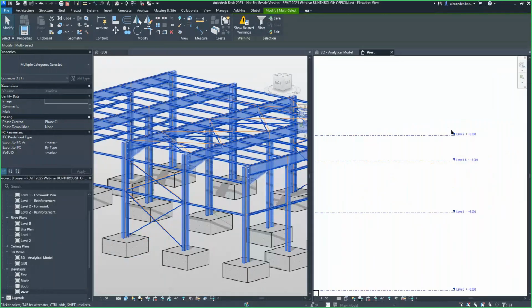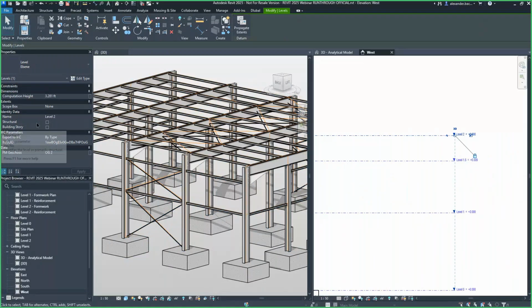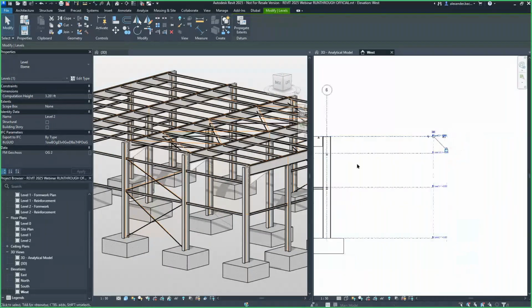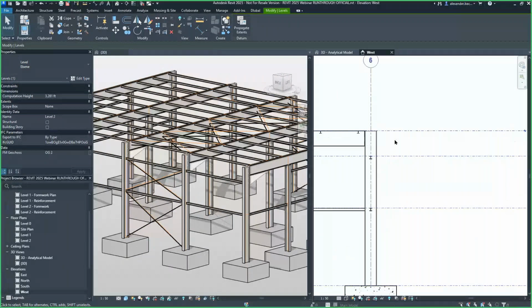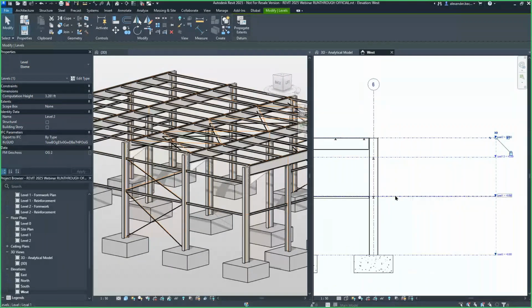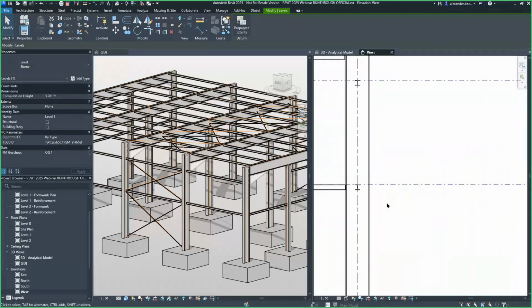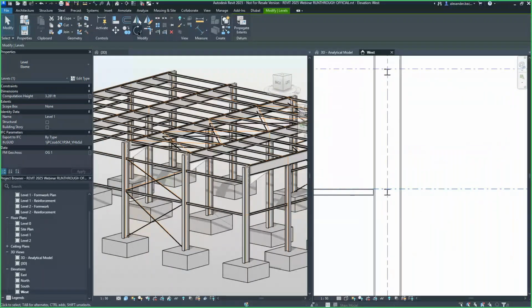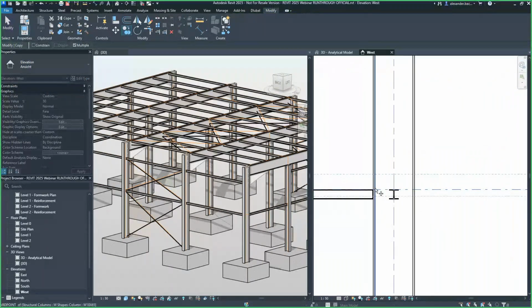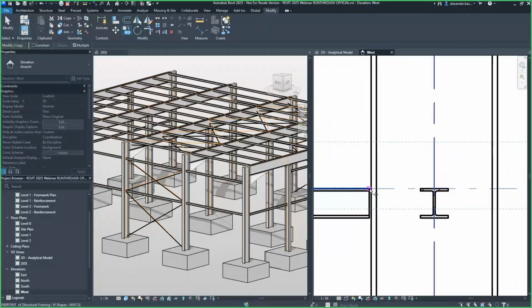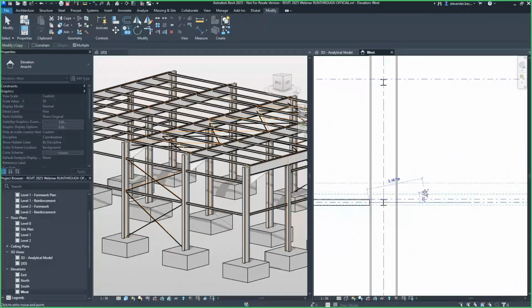If I click on one of these levels, any level that has this structure option turned on. So what I'll do to utilize this option is I'll create some copies of my levels and activate that option. So this first level, I'll just go through, create a copy, and then I'm going to move that copy down like so.